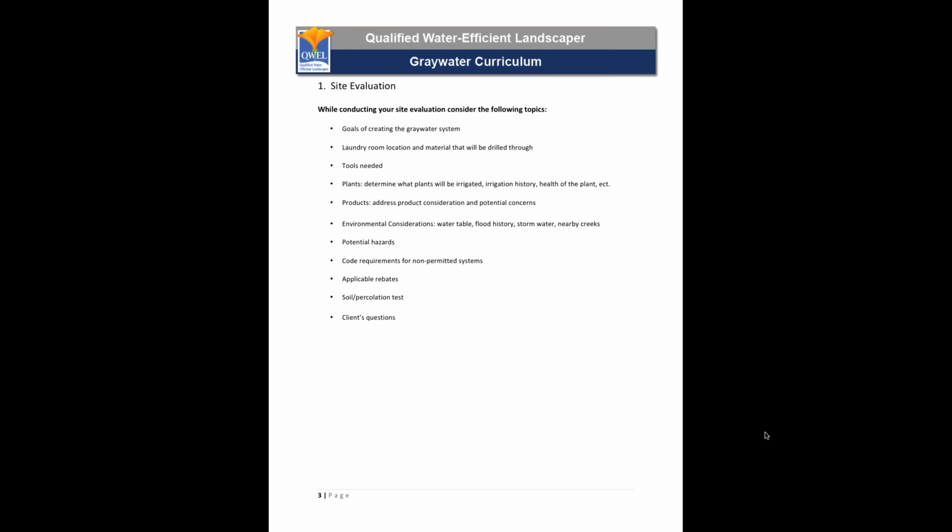As for the soil percolation test, I think you guys recall that we are going through some back and forth with the city of Fresno regarding the soil. So they were really concerned that there wasn't going to be a high enough infiltration rate in the soil, and that would result in ponding or runoff. Ponding and runoff is probably the biggest hazard to human health and safety that gray water poses.